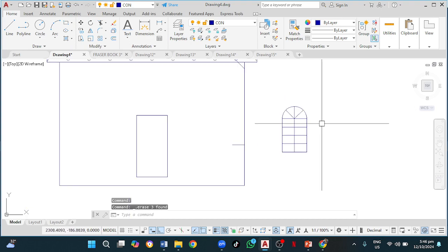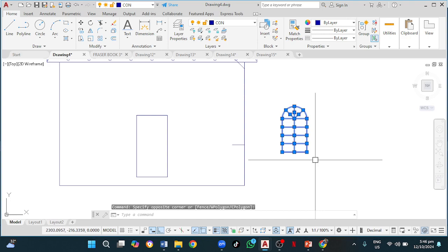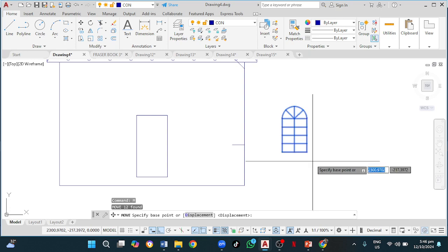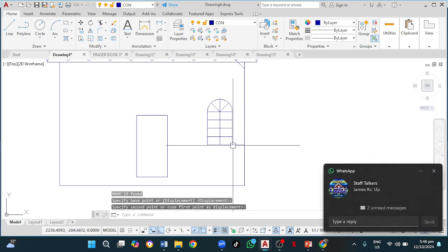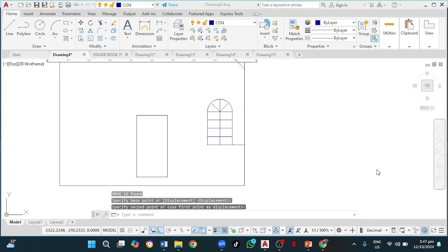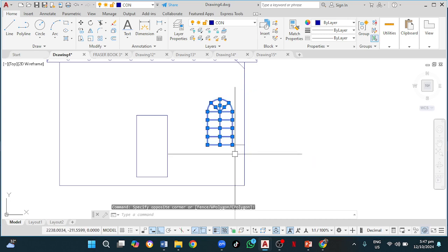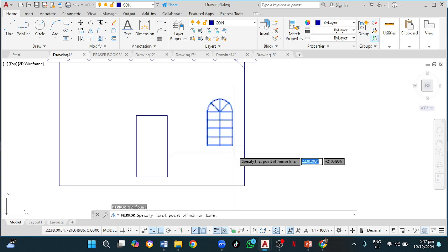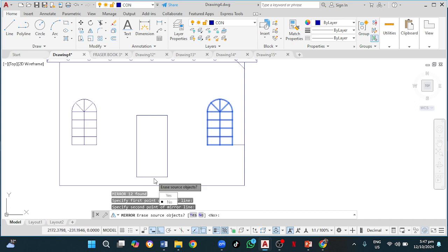That is now done. Now I'm going to move this in the drawing. So I left click here, then drag, left click, type M for move, enter. I now choose 0 as the base point. Then I click right here. That is there. I then mirror this. So I left click here, MI for mirror, enter. I choose the middle right here, there, enter.